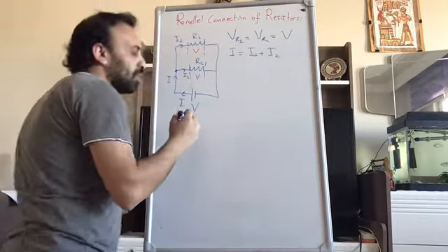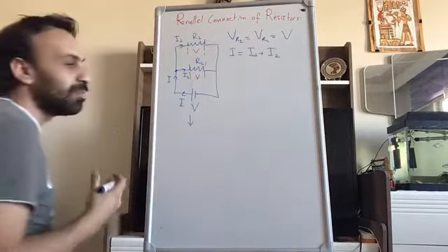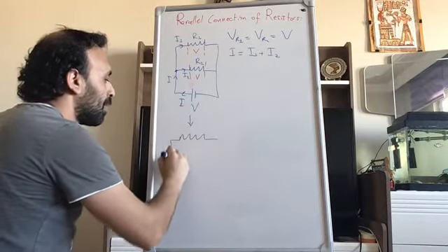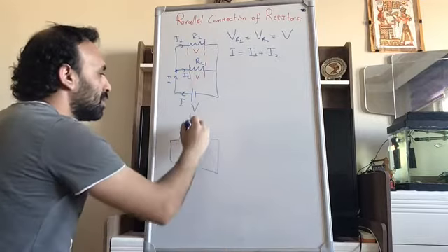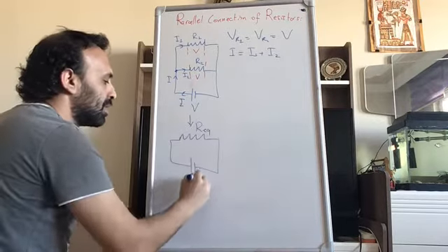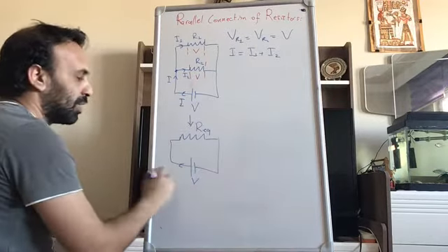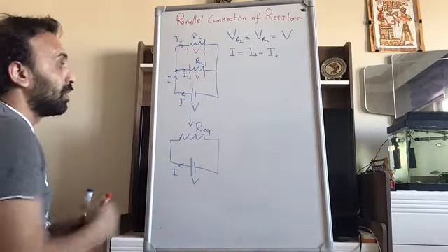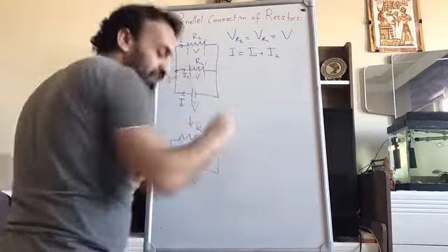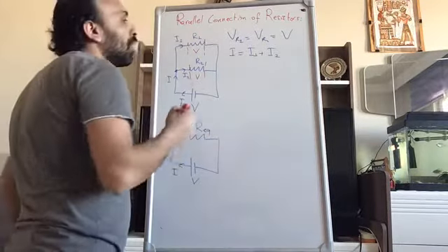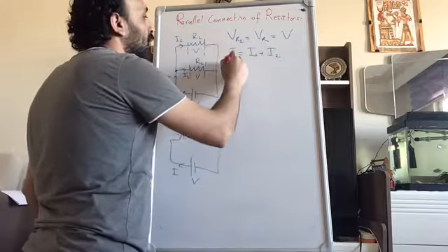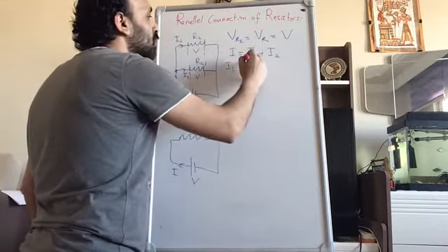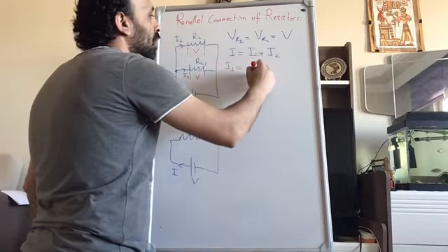Okay, you want to construct a simpler circuit with only a single resistance. So I'm going to call it R equivalent, with the same electric potential and same current. So what is R equivalent? Now let's first write, we are going to use this equation, but by using Ohm's law, I1 will be equal, from the first one, V over R1, right?